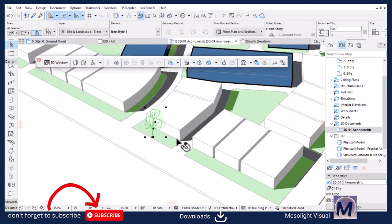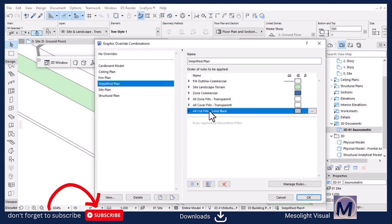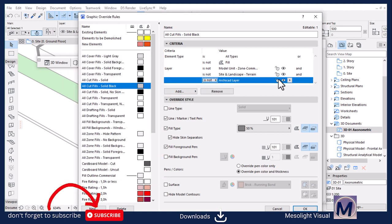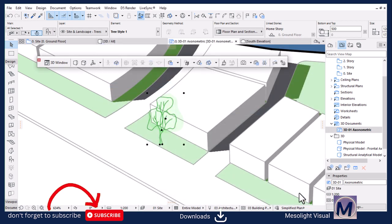I think you don't see the results because it's been overruled. Remember, you have to go back here again and set an exclusion for the trees. Let's edit the rule and add a layer, and then it's not for a layer called site landscape and trees, and then hit OK.